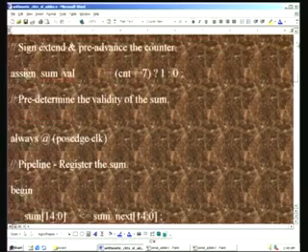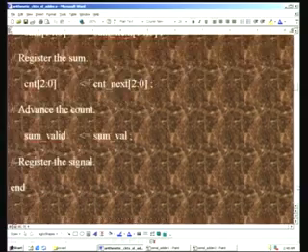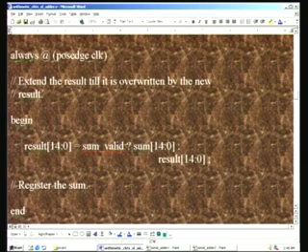This is the positive edge of the clock here, and only the subsequent clock will be reckoned here. When that happens, it is merely to delay the final result by 1 clock pulse, and this actual sum, which was registered in the previous clock edge, will be assigned to the final result. If the sum is not valid, that means it is not valid for a count right from 0 through 7, and it will be valid only for 7. So only for 1 clock duration will the sum be assigned here, which is the final added up value of all n0 through n7.